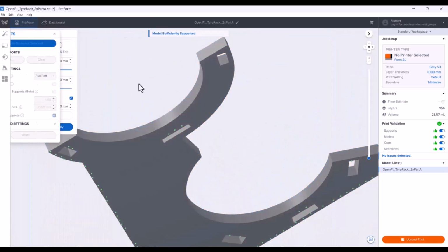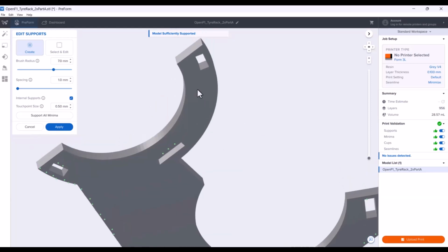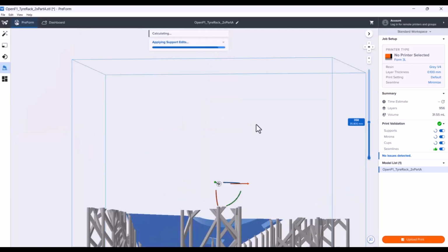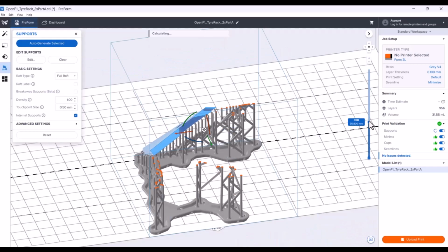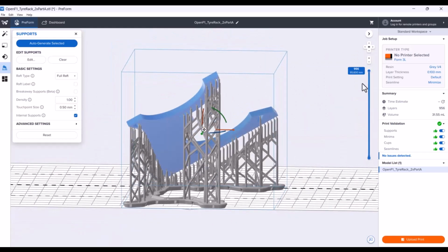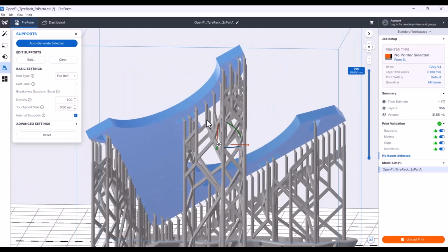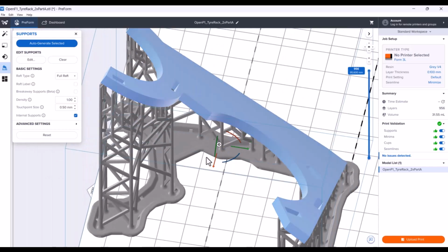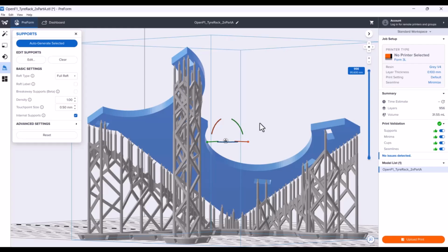I might, just in case, just because I'm paranoid, actually generate some supports, because this is kind of a thin walled surface in there. Get that one off, and that one off. I may actually go in and print this part and see how this looks, kind of test how flat it is, at least on this face. Kind of go from there.